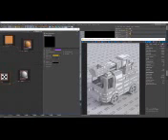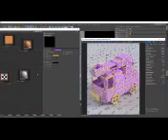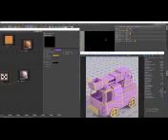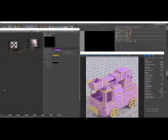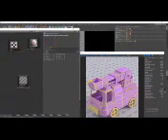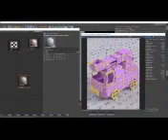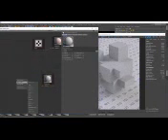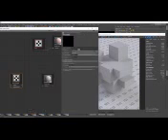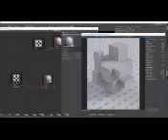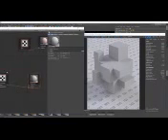Now let's stop the render and hide the truck and unhide this geometry called cube extruded and assign a new Corona material to it. Finally, we have this round edges map. So let's load one, and we need to connect this to the bump map input of the Corona material. Let's set the radius to about 2 centimeters.